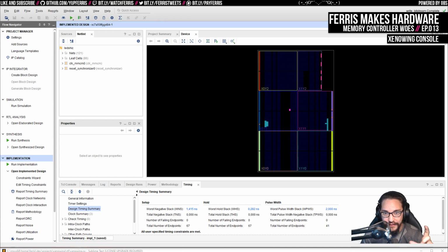So I basically turned off the lookahead. You can have it do lookahead for the commands that you're issuing. So if you issue a bunch of reads or writes that are going to rows in memory that are sequential, then it will batch those and it'll be able to do them faster. So you end up with better throughput through the controller, which is the kind of thing you want. So anyway, it ended up being this really frustrating process, and in the end, I got a controller with worse performance that I couldn't even tweak on my main machine.